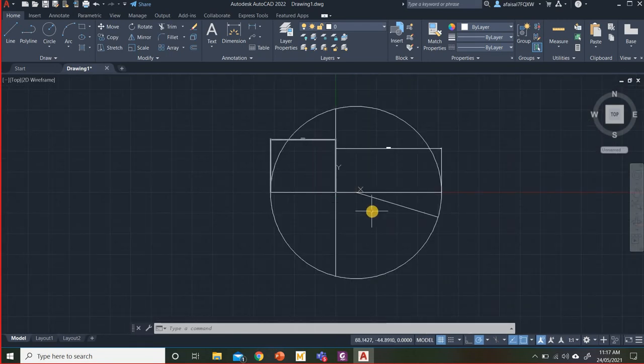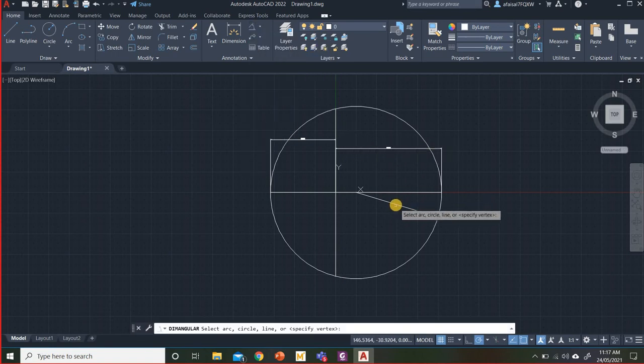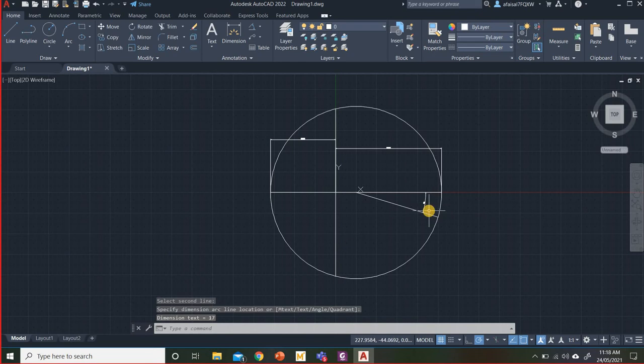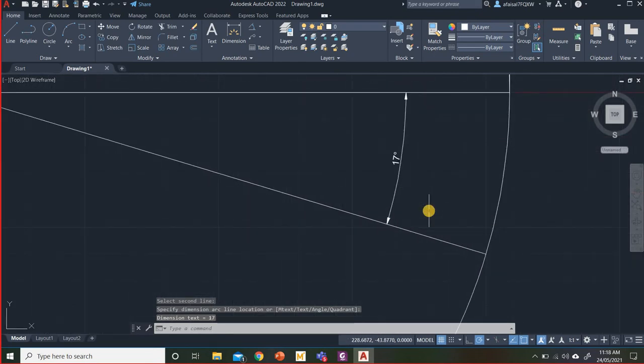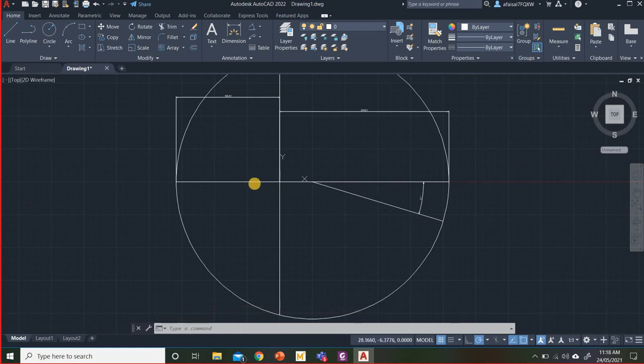Now, what about the angles of these values, the major principal strain and the minor principal strain? You can come over here to the angle, first line, second line, and you can see the angle over here. Okay, 17 degrees. This is 2 theta 1. Similarly, you can also see the other angle if you like, but one angle is enough.